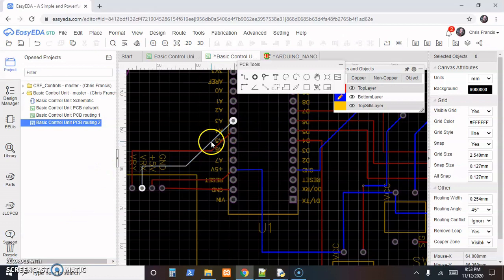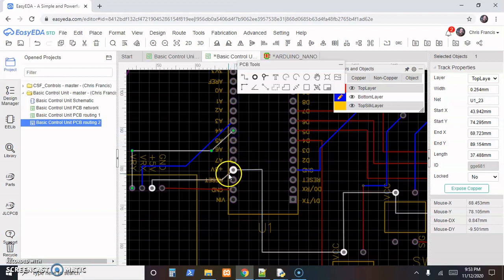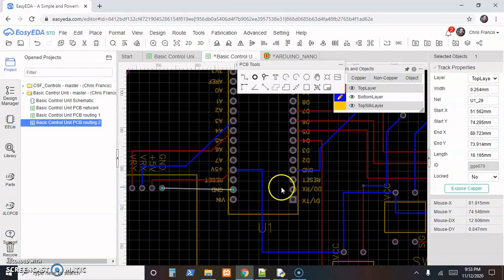Okay, so I think I got all this corrected, but to check, I like to grab the little endpoint and drag it away and make sure all those connections are still there for all the pads. It happens sometimes. Little issues show up and might have to make modifications. So this is one network, so I can just drag that over there. Yep. And just make sure that there is still a connection going to every pad, because that will be very important. Otherwise, when the machine prints that out, it wouldn't. Yeah, that's how the machine knows where to make connections.